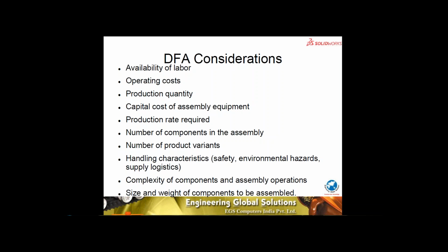The design for assembly considerations, I will give you a simple example. If a component requires 6 fasteners, 6 M12 bolts or M8 bolts, let us say, if we are able to reduce it to 4 M10 bolts, then 2 fewer drillings need to be done in 2 different components. If it's a fastener with a tapping on one of the components, tapping operations are eliminated for 2 of them.